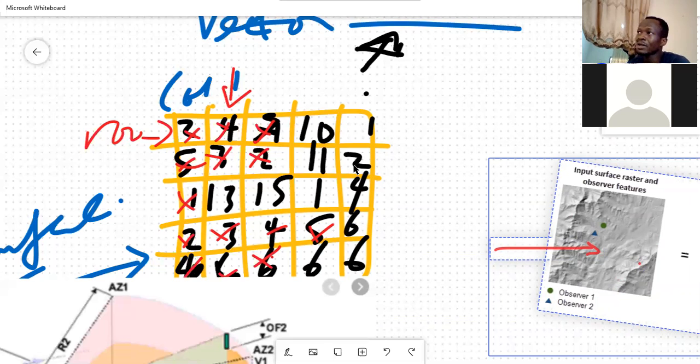And then you now find out the most suitable areas where it is prone, like where water is likely to accumulate. Okay, and it has to be based on the surface. You have to get data on the surface itself. Then you need to get elevation data as well. Then you need to get data on drainage in the area as well. You need to take all these data and then cost them. So the areas with the highest cost will become the areas that are prone. Are you okay?